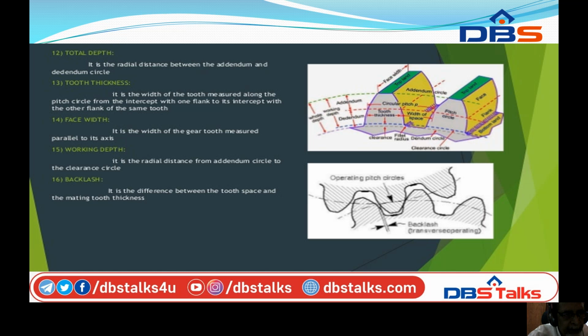Working depth. It is the radial distance from the addendum circle to the clearance circle. Then backlash, it is the clearance between the tooth space and the mating tooth thickness. So these are all the different parts of the gear tooth.